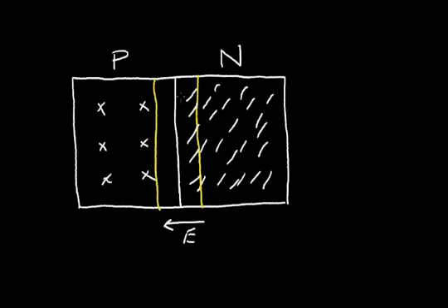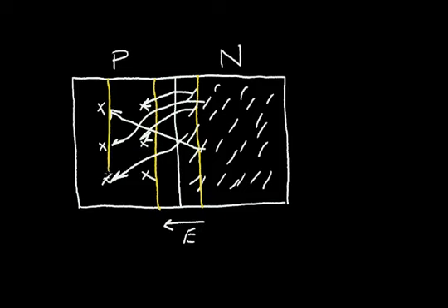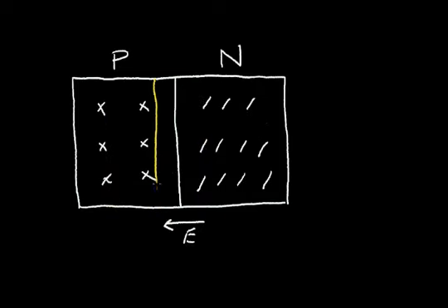Well, what's going to happen is these electrons have to migrate further into the P material to recombine with the hole. So that these electrons will maybe have to wander way over here to recombine. So what happens is, because this region, the P region, is lightly doped, that the depletion region is depleted of carriers.